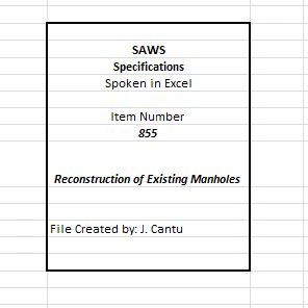3. Any measurable loss within a 30-minute period shall be considered an unsuccessful test and thus require the contractor to assess the needed repairs, perform such repairs, subject to the approval of the engineer, and notify the inspector when the retest will be performed. 4. All effort, materials, or other costs shall be solely at the contractor's expense. B. Vacuum testing.